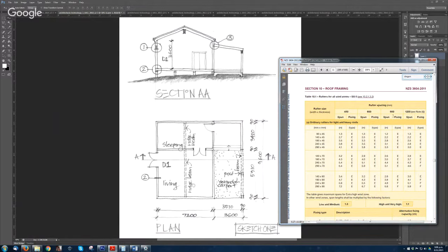So you look at here, then you go down until you reach 3.6. So it's going to be this one here, 4.4, and then the size of the rafter is going to be 240 by 70. You can also use 3.8, which is lower down, this one here, 190. They're both correct. You just need to be more than 3.6.